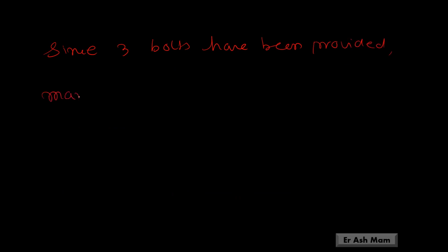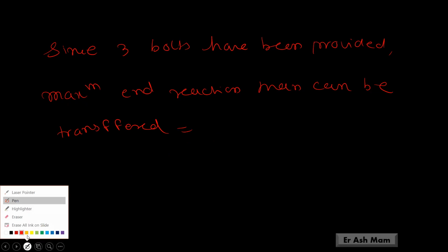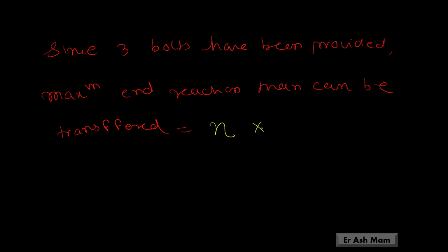So it means, since three bolts have been provided, the maximum end reaction that can be transferred is equal to number of bolts into bolt value.